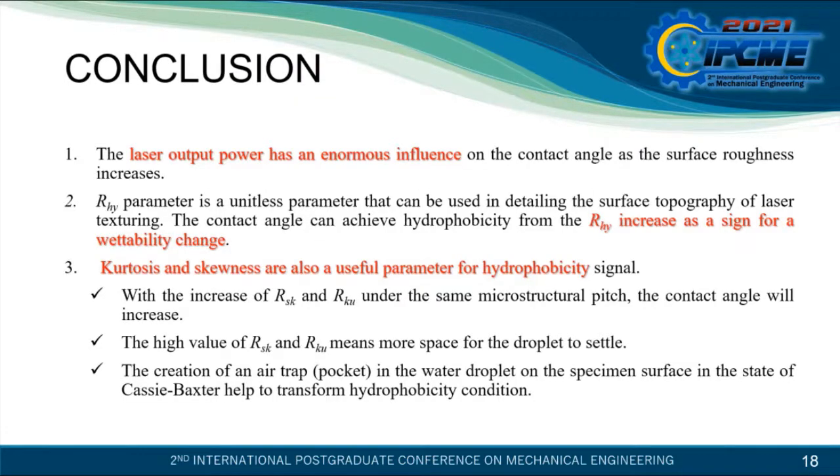A nanosecond laser texture on stainless steel 316L was studied to see the effect of laser power and surface roughness on hydrophobicity. The maximum contact angle that can be achieved is 125 degrees with the output power of 24 watt, calculated on day 13 of 30. As a conclusion, one, the laser power output has an enormous influence on contact angle as the surface roughness increases.